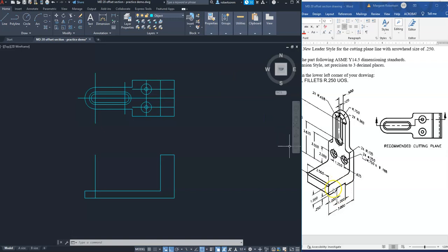Now let's put in this notch at the back, whatever that's for. And what is it? It's 1/4 of an inch deep and down an inch, down an inch. Okay, so let's get O for offset, and a distance of 1/4 or 0.25. Select line on that side.